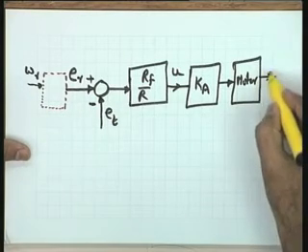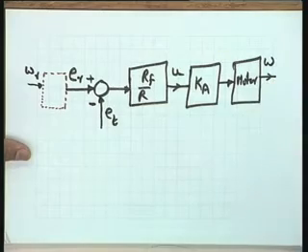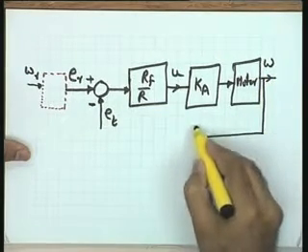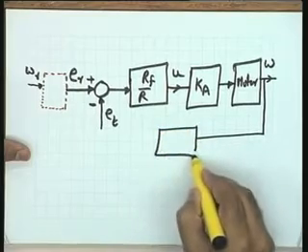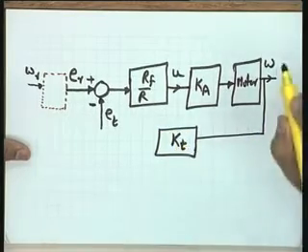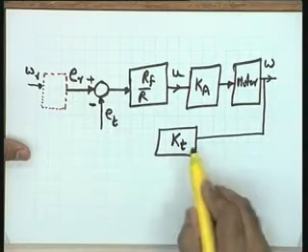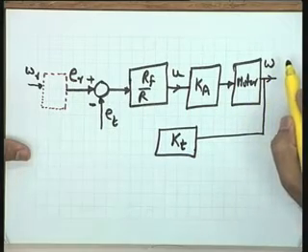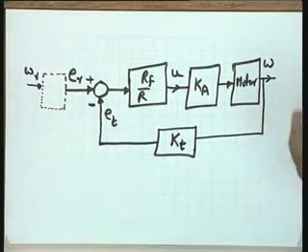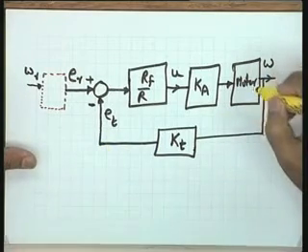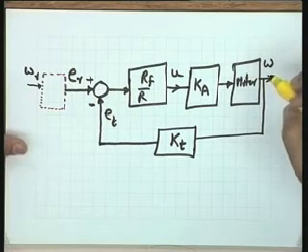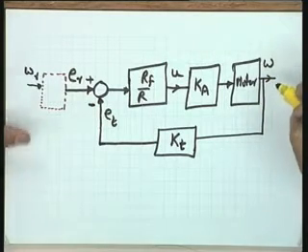The output here is the controlled variable omega, okay, and this omega is being sensed by the tacho generator, which is a sensor, and let me say Kt is the constant of the sensor. So, that Et is equal to Kt into omega, and this is being fed back here. This is the basic block diagram, but for the motor block to be opened, to be detailed properly. So, I am going to give you the transfer function of the motor block.